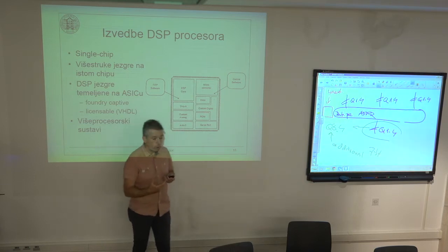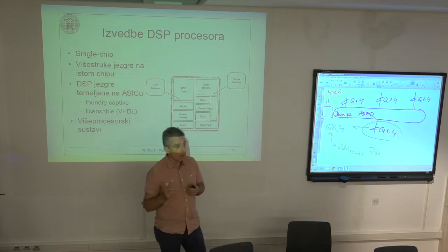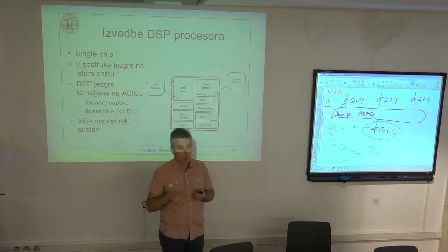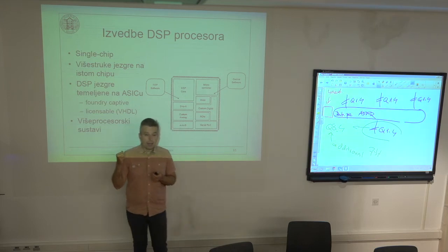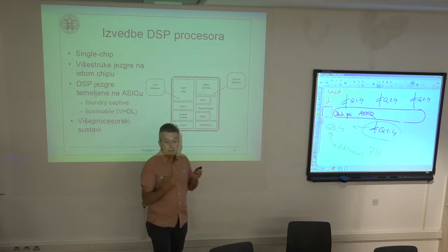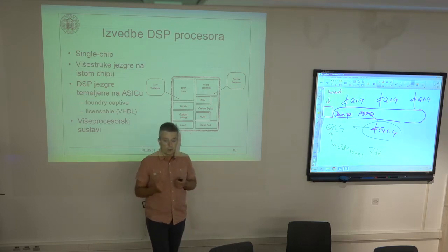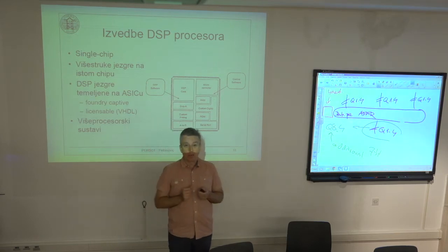Two component vector or 4 component vector. So if it is some kind of SIMD architecture, single instruction, multiple data, this multiple data is a vector of 2 elements, of 4 elements, maybe 8 elements, but not more than that. On the other hand, on these field programmable gate arrays, you have the same basic underlying architecture of multiplier accumulator unit, but several hundreds of such units are available within one chip that can be connected into a very complex design.